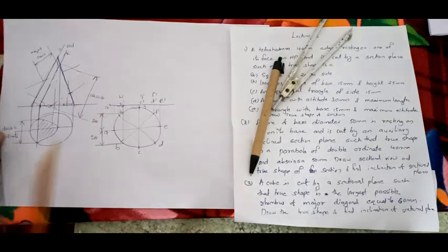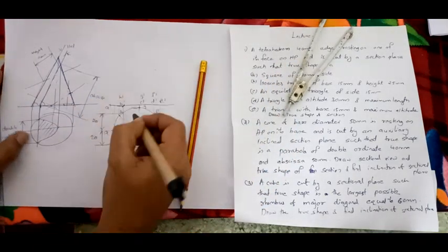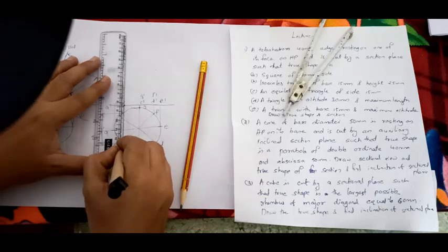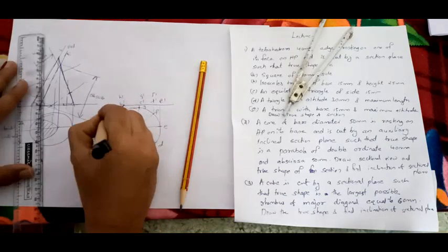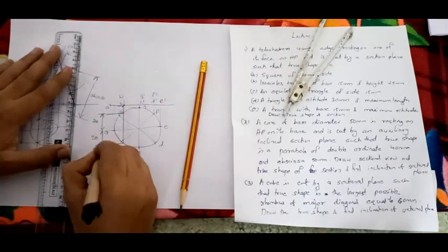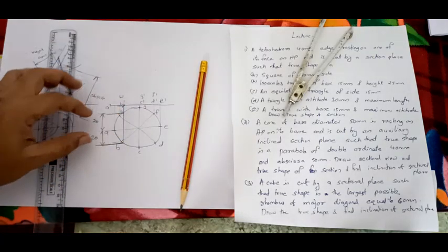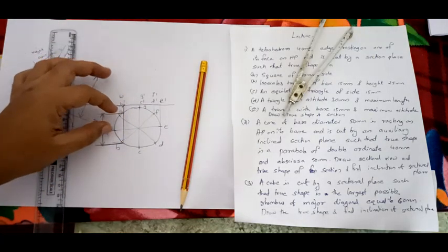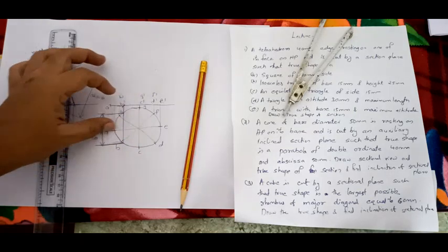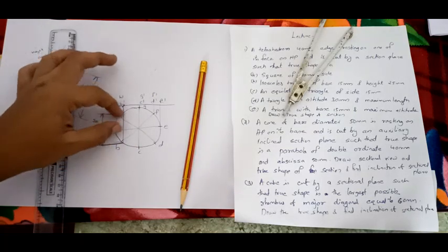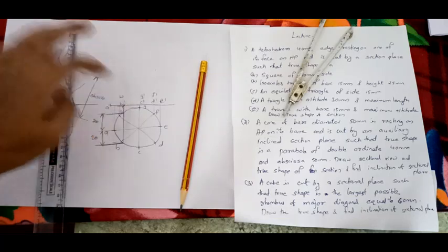So this point we have obtained. Now I'll draw this. For better visibility I am using a pen. By using the 40 mm double ordinate given from the center line, I have taken 20 mm towards both the ends and found this point.